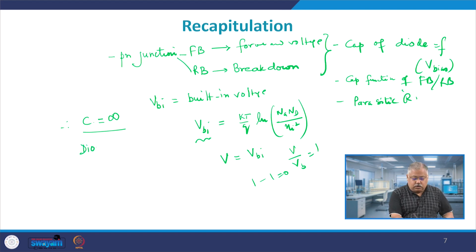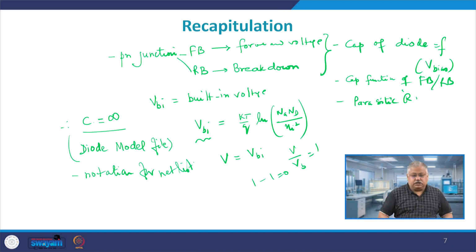We looked into diode model files, right. These diode model files have been looked into, and also we looked into the notation for netlist and how these notations are important. And at the end of the talk, we discussed the two practice circuits. Try to emulate them on LTSpice and then try to get the values of the voltage and current in this case. I think with this I will stop at this stage and we will continue with the device model in my next class.